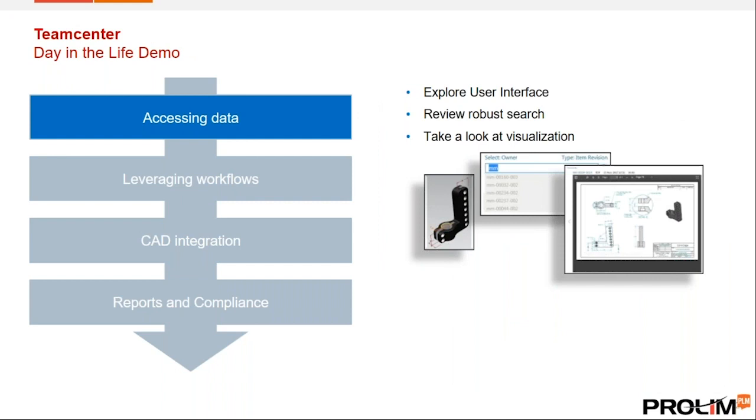So as we talked about, as you find a particular part, you can see it's got its own embedded viewer on the right hand side. We will show you in a minute. Then you can see its visualization. If it's a CAD part, if it's a corresponding JT, you can look at that. You can do operations on that JT file: pan, zoom, rotate. You can cut sections, you can measure, you can get the properties of the surface or hole, whatnot.